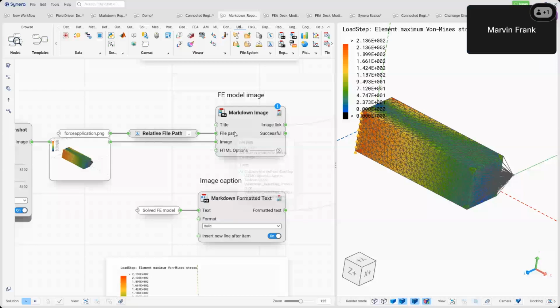For this, what we need to do is some basic text matching. So we first search for the grid. As we can see here, we search for this first entry. Then we split that file into 2 parts. Basically everything that is under the bulk data section, everything that comes afterwards. And we take the deconstruct bulk card of this first line here, and then we see that, nice, the y coordinate of that grid point actually is the fourth item here, or for the index 4.